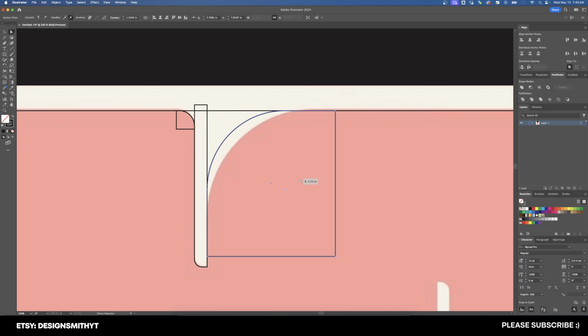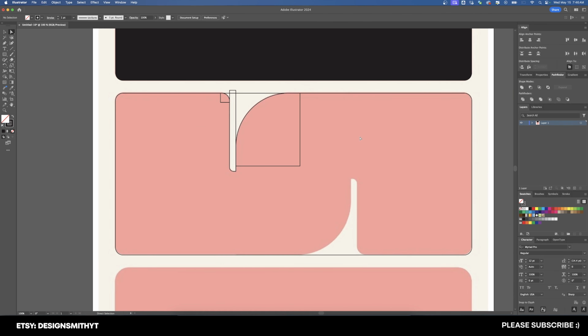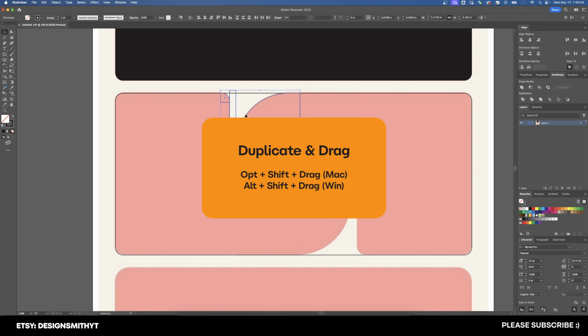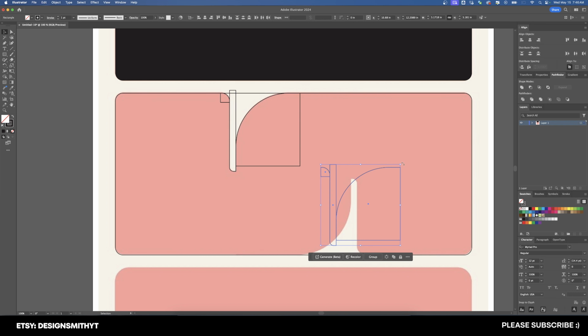And we're going to manually adjust this one all the way down to here. So that's a little over 2 inches, so we'll just say 2.1, just to give ourselves a nice round number. Okay, and now I'm going to select all 3 of these, hold down Option or Alt on my keyboard, and drag this down here, so that these both have the same exact parameters.